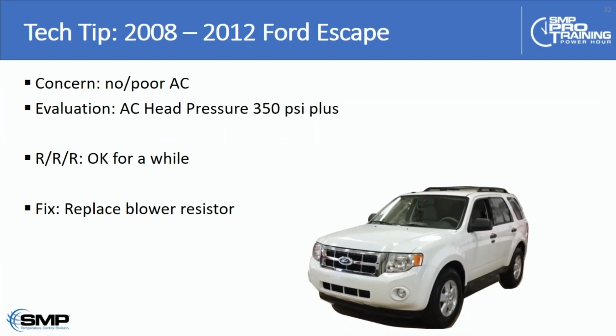A quick tip here, this is '08 to '12 Ford Escapes. You can get repeat blower motor resistor failure, and the customer may also complain that the air conditioning barely works at all. When the technician checks it out, high side pressure is usually 350 psi, give or take, and nothing obvious is found. The shop recovers and recharges the system. It works okay for a while, and it comes back with the same symptom a week or so later.